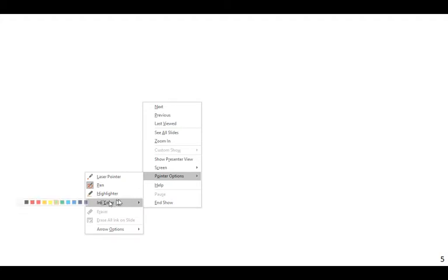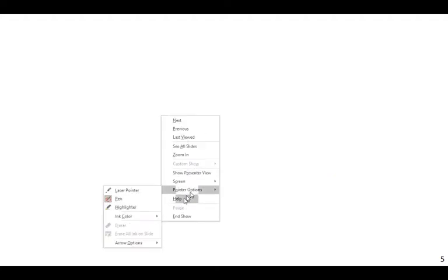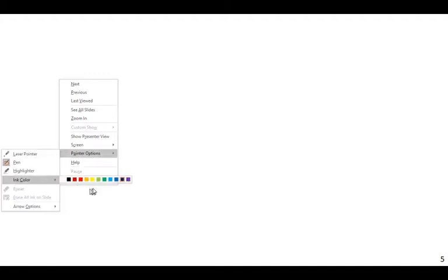Okay. So next, I'd like to discuss a bit what this Ubs thing is. So all this stuff here, net shear area, net tension area, gross area, that's all fairly straightforward. But Ubs does need some discussion, and the commentary does go into this in great depth, greater depth than we'll have time for here in class. But I do want to discuss what this factor really means.